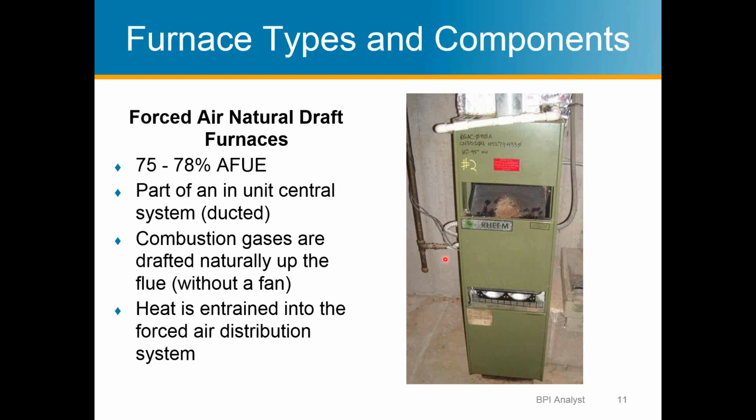And then there's going to be a heat exchanger here where the heat rises up. And then this is where, again, you would check for spillage right around here, to see if any of the exhaust gases, as they come up, spill out. But this is where extra air is added to the exhaust, and then here's your exhaust system.